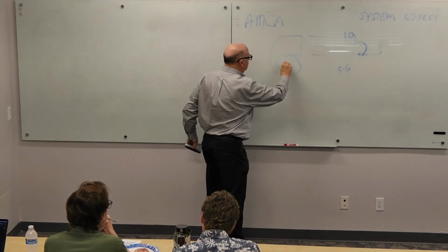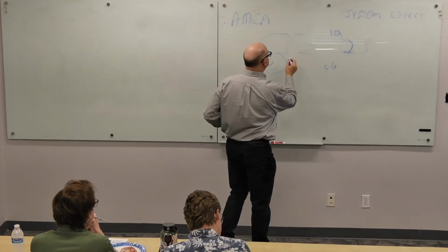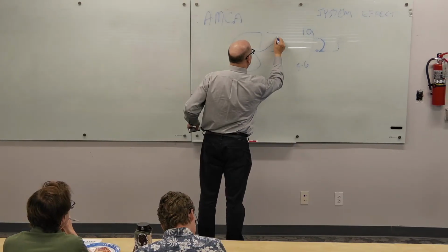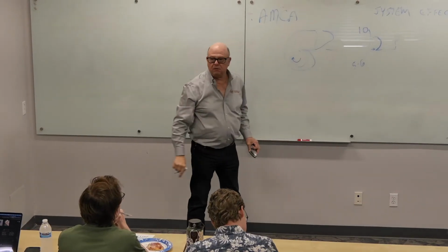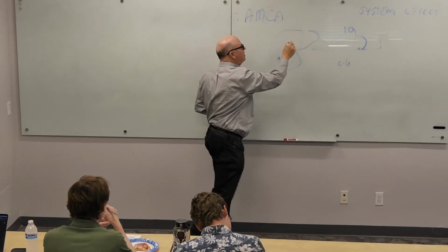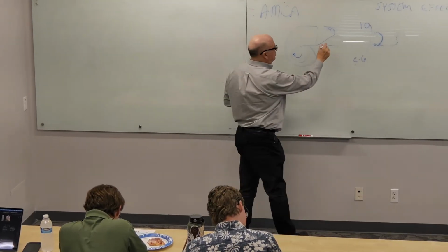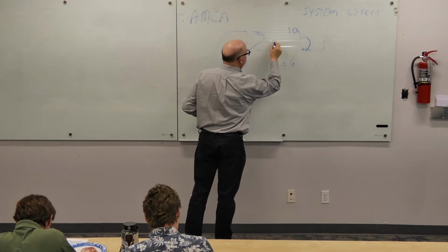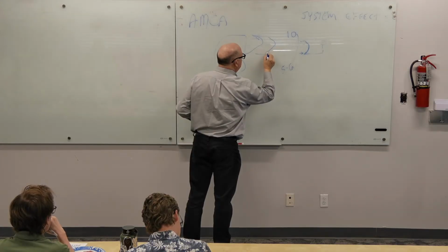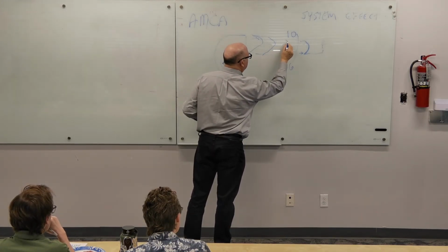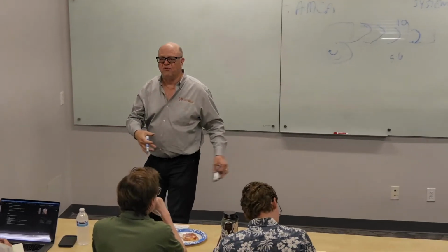But with this fan wheel spinning like this, when it first comes out of that fan scroll, it's like this, right on the discharge. Because, right, you can just see that centrifugal force. And so you've got a lot of velocity right there. And then as you go along, it gets better and better. Maybe it's more like this, and then it's more like this, and then eventually, you see the trend as you go further down the duct?